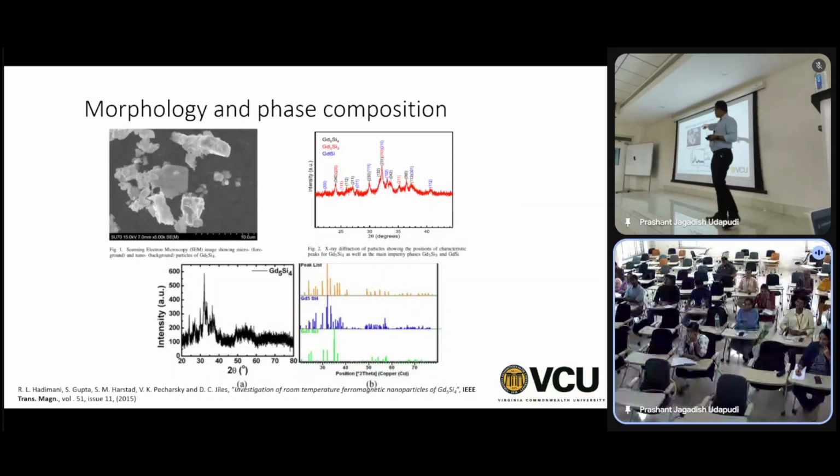Okay, so that means when we did ball milling, we changed the chemistry a little bit, and we got some impure phase, right? So this is how you characterize the powder, so that when you use it in additive manufacturing, you get the material you want. Okay, and again, here is the reference peaks of different phases. When you don't clean the signal, this is how it looks like. And when you remove the noise, you get slightly better signal.